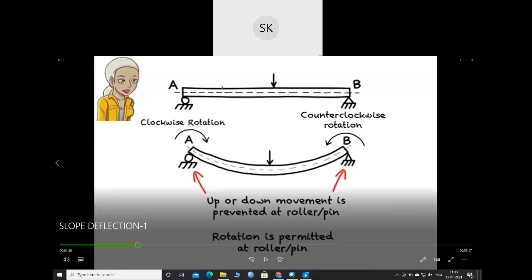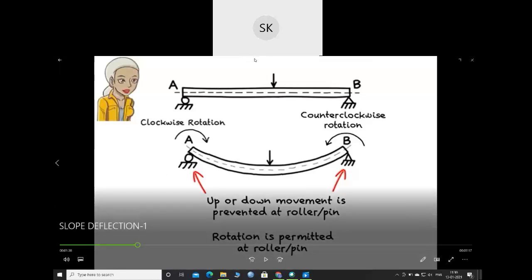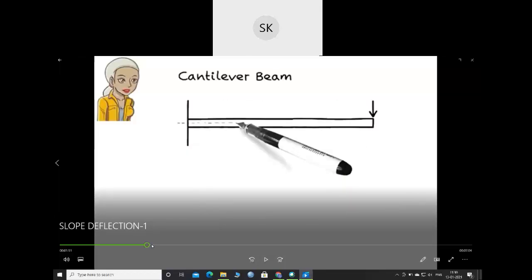Note that a distributed load defines a geometric area. For example, in the case that the load is distributed uniformly over the length of the beam, the load forms a rectangle. Here, the base of the rectangle is the length of the beam, and the height of the rectangle represents the load magnitude. Since the load magnitude is given in force per unit length, the area of the rectangle, base times height, gives the total load applied to the beam.